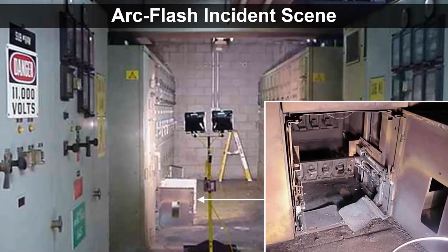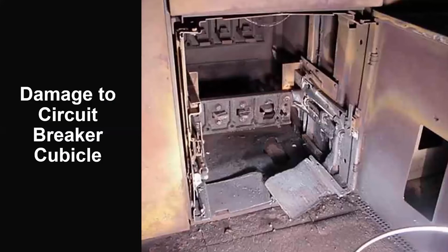So taking a closer look at the damage to that cubicle, you can see it's completely charred on the inside, and you can see these burn marks on the top of this cover plate provision right there. Based on the records, it was found that first the rightmost phase came in contact with the ground and quickly escalated to 2 phases and then became a 3-phase arc. And it's not uncommon for an arc flash incident to start off with a single conductor exposed to another conductor, and then immediately evolve into 2 conductors and then 3 conductors and so on, because of what I mentioned earlier. It just weakens the air around it, and then suddenly the air becomes a conducting path and creates an arc around it, and things quickly escalate and cause this damage.